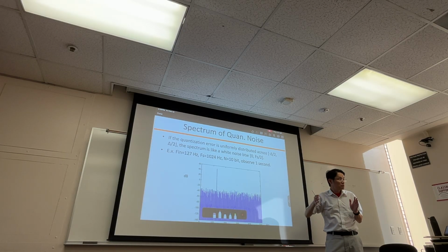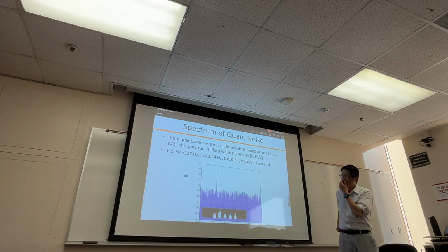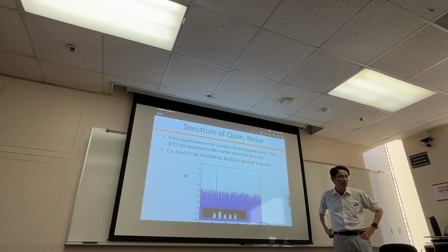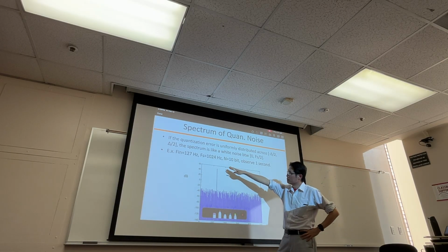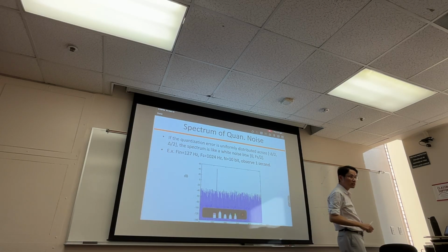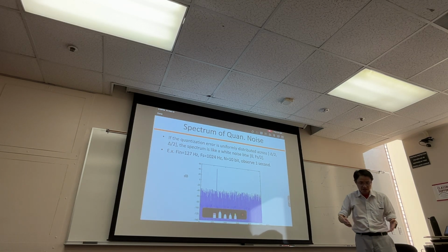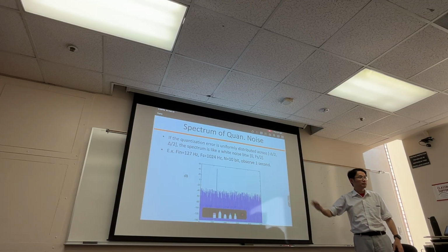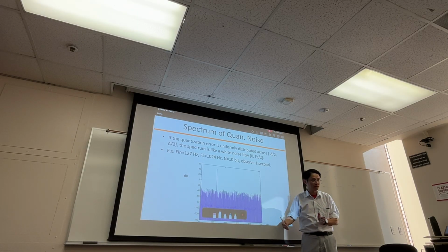I'm going to collect samples. Actually, how many samples do I collect in this MATLAB? Input 127 Hertz, sample rate 1024 Hertz, 10-bit ADC, I capture exactly 1 second. I try to mimic this ADC as if in real life it runs for 1 second. I don't mean that my MATLAB simulation time is 1 second. That's not what I meant. I created the MATLAB to mimic as if I run this ADC for 1 second. How many samples do I collect?